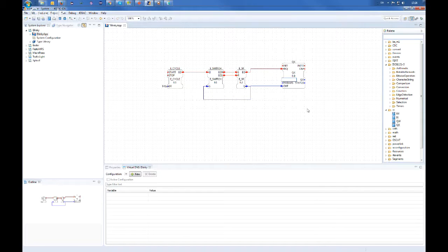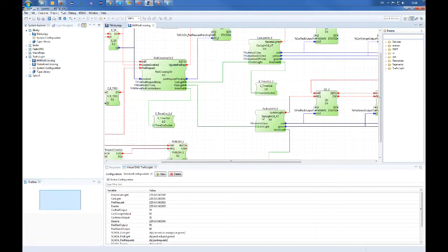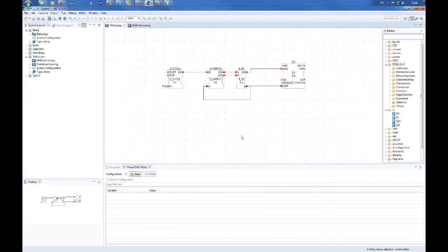We have an input that says if it should initialize or deinitialize. And we have a params input, which tells which output of our Raspberry Pi we should use. To be honest, I have to cheat a little bit and look in my old standard application. The orange light has output 60. So we will write 60 here. Good, so this would be our application.